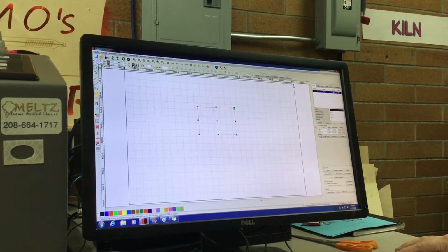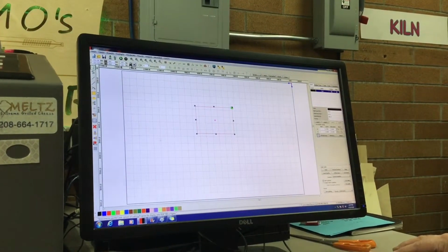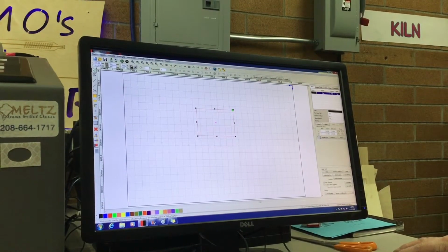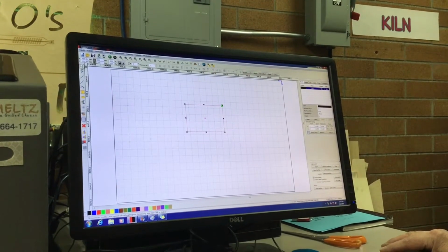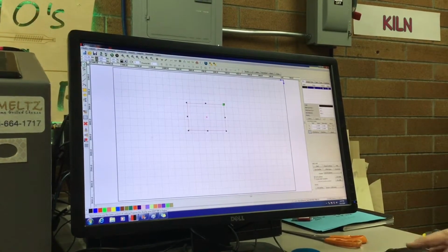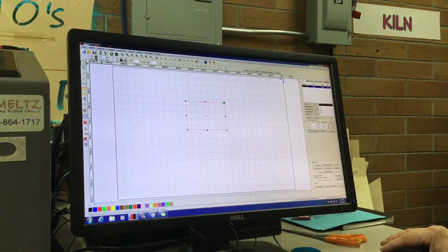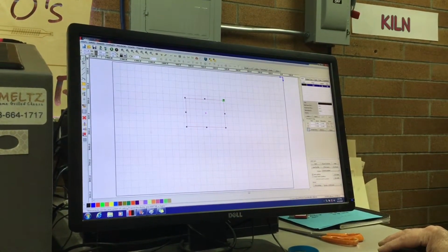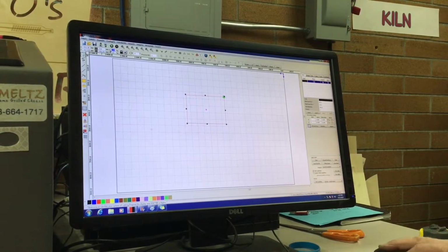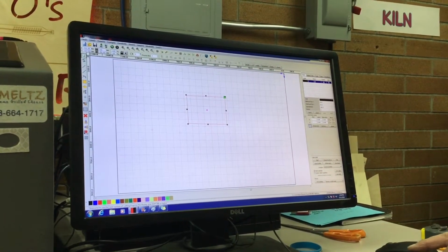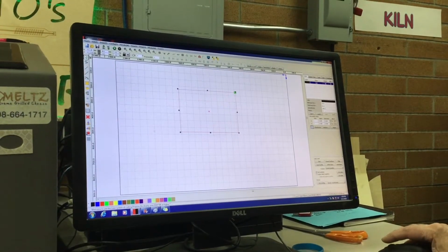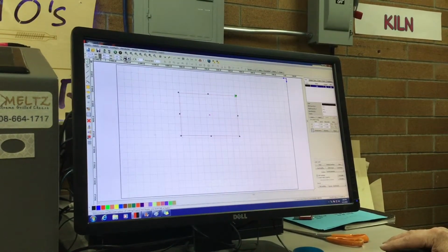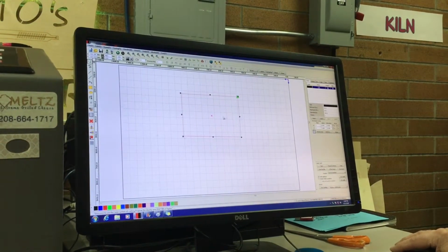If you want it to stay that shape, but you'd like to change its size later on, you can click on the lock symbol and say you wanted it to be 310 millimeters, you could type that in here. Let's do that, 310. So now it changes the 310 and the 200 millimeter dimension to stay in the same shape. You can also just introduce a percentage increase in it. Say we wanted it to be 50% bigger, so we type in 150% and it gets bigger like that, but stays the same aspect ratio. It's always possible to unlock this and be able to go back to changing it independently.